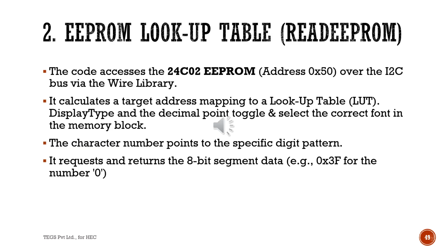The character pins point to the specific digit pattern. It requests the return of 8-bit segment data, for example 3F hex for the number 0.